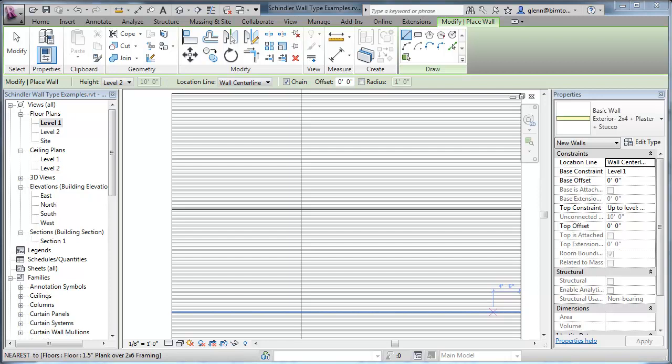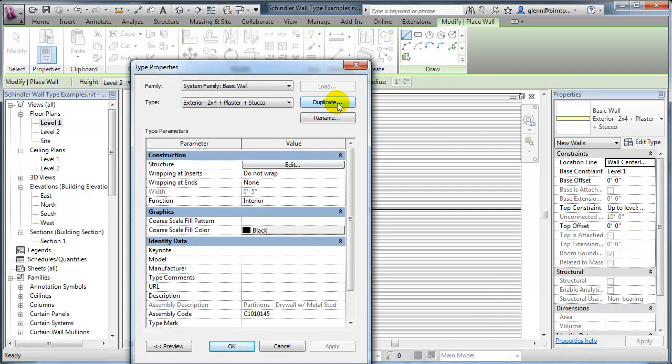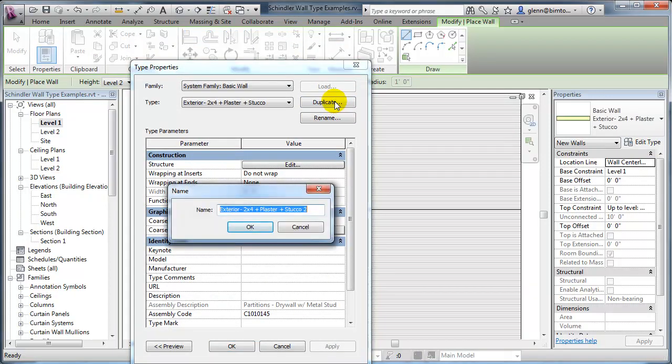The last 2 different wall types that we want to create for our little samples are those top wall conditions. There's a 2-inch thick wood one, and also one that has wood and a little bit of plaster to level it out with the surface. So let's create some more wall types. I can just edit this type, and I will duplicate this, and I'll call it upper.